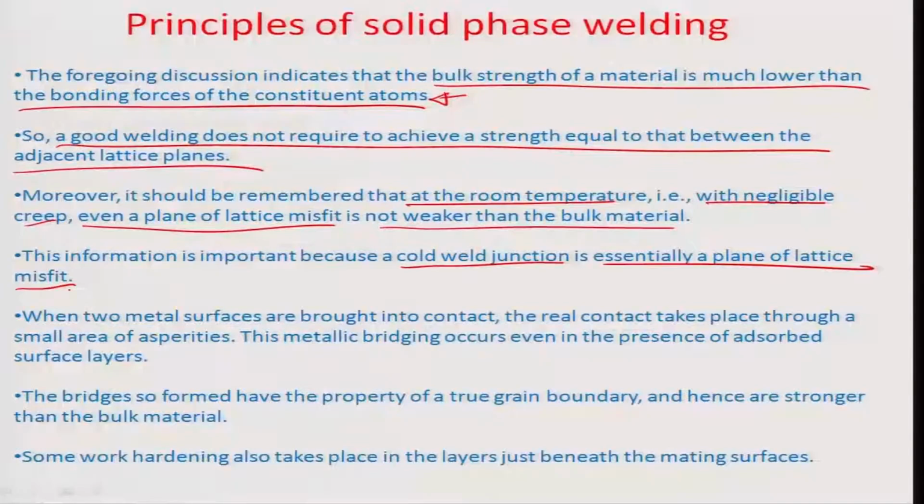huge pressure. And so, the contact, if we look at between the two planes which are being brought close together. Let us say we are welding these two surfaces with respect to each other, by applying a vertical pressure in between the two. So, there are the small asperities between the surfaces which formulate the real contact. And the metallic bridging kind of a thing happens here, that supposing there is one contact which is like a hill and another which is again like a hill.